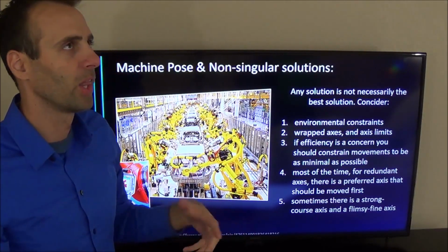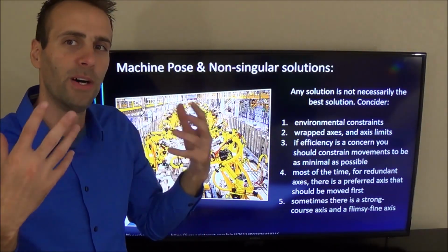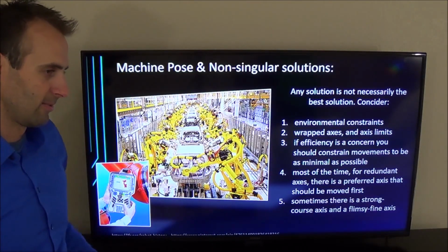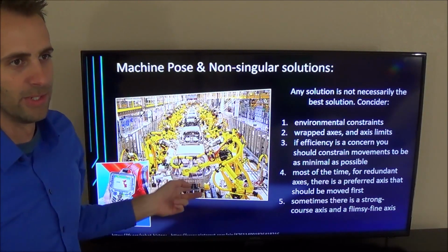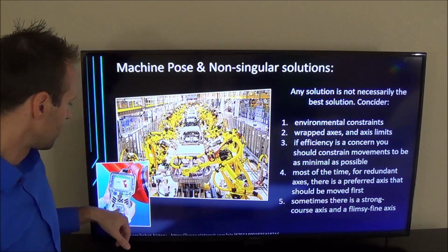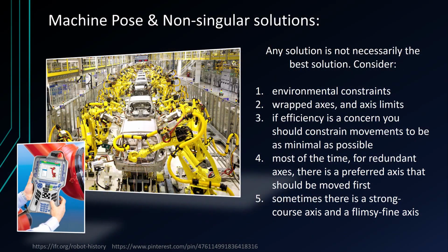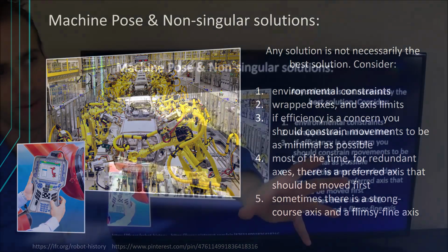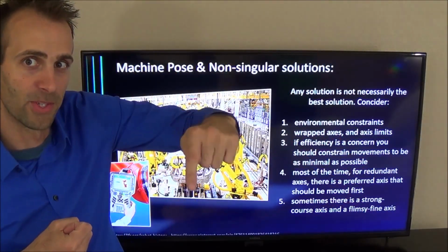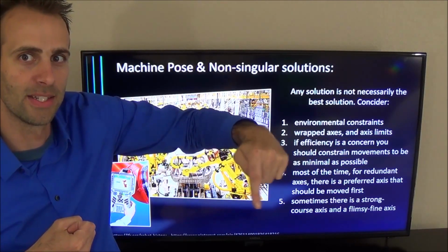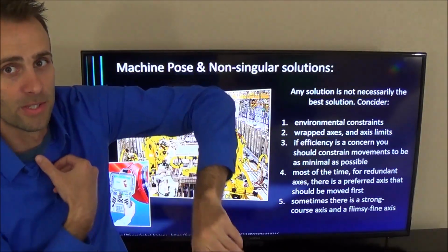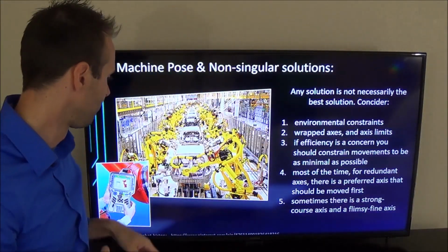So there are a couple of things you need to think about while going through that methodology. And just to be very clear, they don't do this mathematically, no. What they do is use this remote, drive my arm to where it needs to be, put the windshield in the hole, and then say, now mathematically I just want to go from here to here. Or if this is a welding robot, I want to go from here in a straight line to here. So again, break it down: solve your pose first and then do the math, okay?